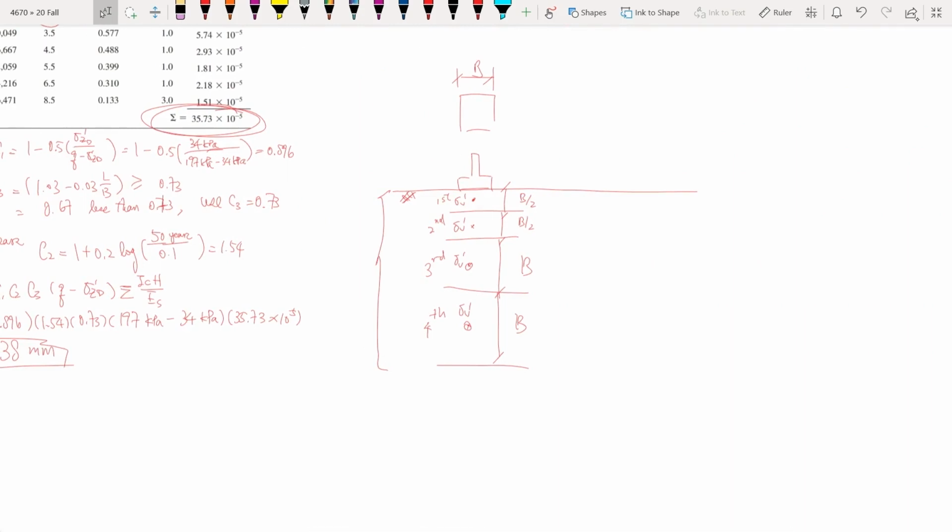So you know the stress before you lay down the foundation, and also you know the stress after you lay down the foundation, with the additional amount of loading at each layer. So the final loading will be equal to the original vertical loading plus the change of the stress, right? Because your foundation gives you the change of the stress. So now we know the change of the stress before and after, then you can perform the settlement analysis.